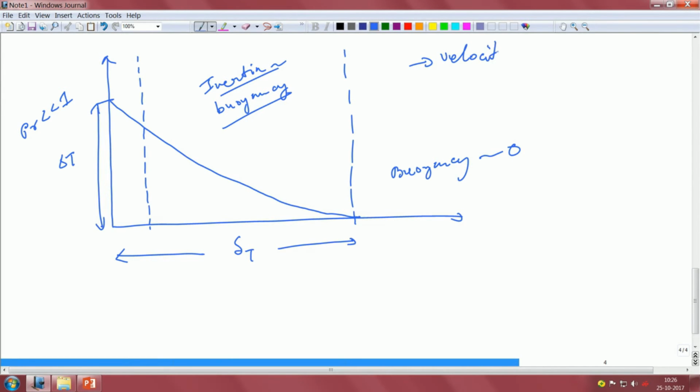velocity profile must be as wide as the temperature profile, right, it should be as high as the temperature profile. So, naturally this dictates that the peak of the velocity would be somewhere in between these two limits, right, these two 0 and delta T. In this limit the velocity must be maximum in some particular location, right.